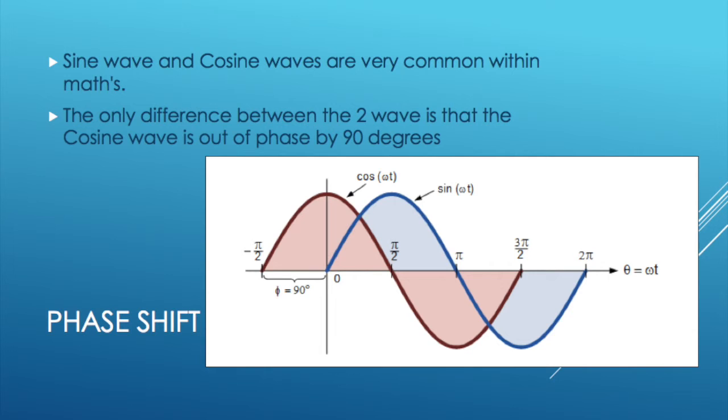Now, if we were to write the sine wave as an expression of a cos wave, we would have y equals whatever the amplitude is, cos(omega t minus 90). Therefore, it's lagging by 90 degrees, as shown here. So if you're starting before, you're adding the phase shift. If you're starting after, you're lagging, therefore you're subtracting the phase shift.